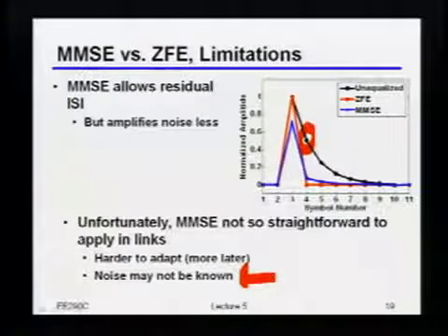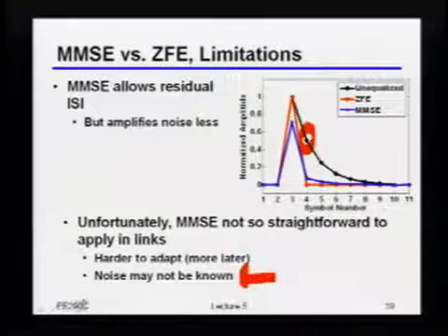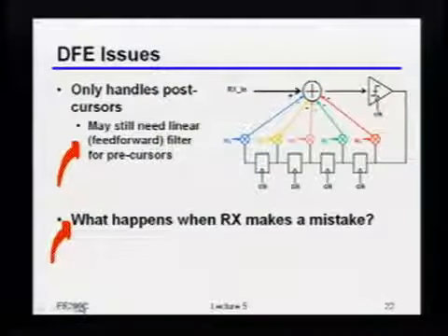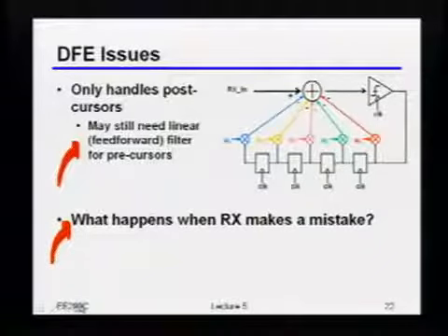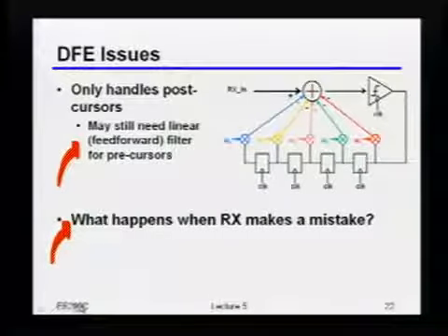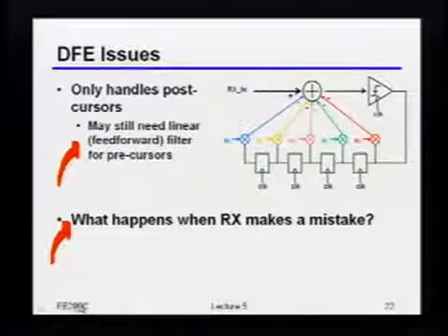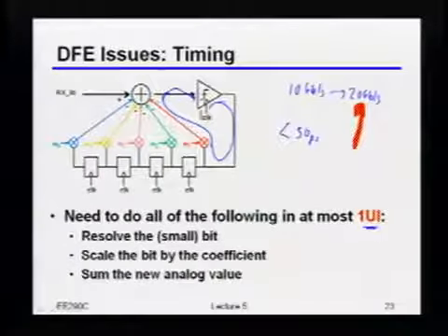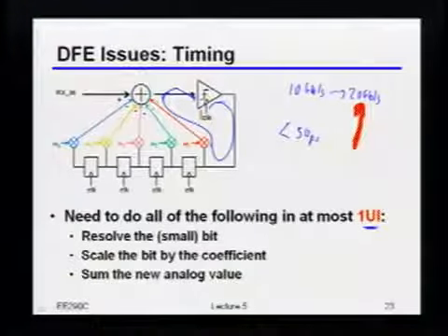Yeah. So to do DFE, basically we don't want the noise amplification, right? So the fundamental difference between DFE and a linear equalizer is only that you don't have noise amplification. But what I mean is, if you have this feedback, you basically have added noise and the input at the same time. You're just saying that, hey, fundamentally these are devices, and those devices have noise. So yes, that's right.